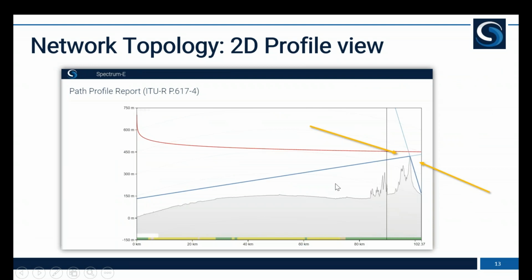Another reason why it's important to have the appropriate terrain information in the tool is because if you don't, you might not be able to get a real-life takeoff angle calculated in the scatter region and so forth. So you do want to have a good resolution in that terrain, so that you're able to see the obstacles, to calculate diffraction if you need to, and so forth.